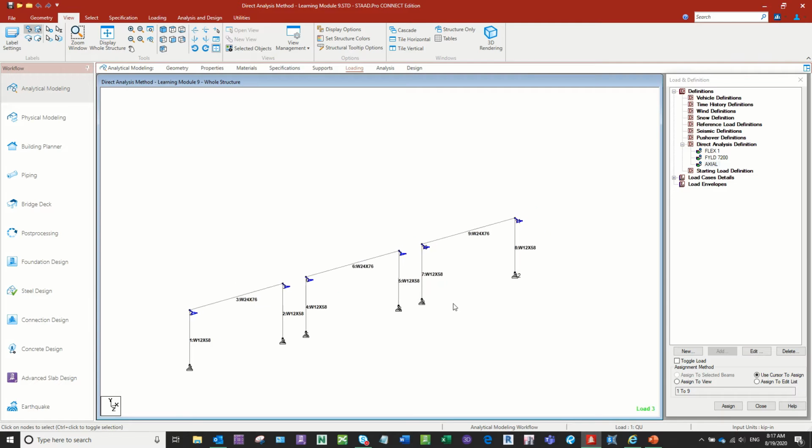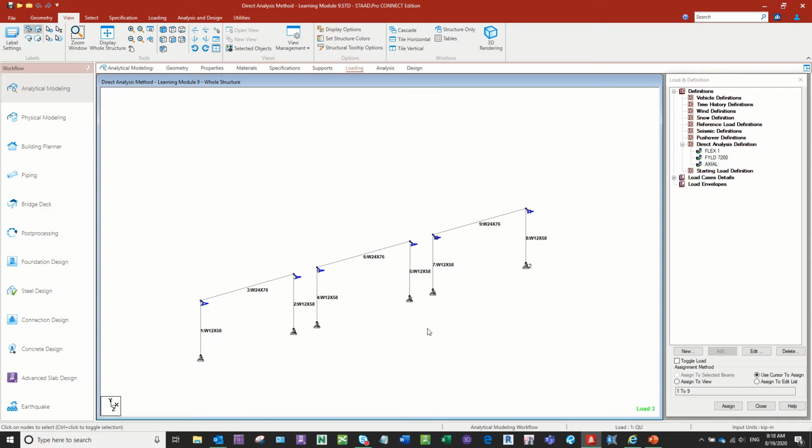And by stability here, I mean, in this case, the ability to maintain its equilibrium, its structural capacity in a deformed shape, and not have extremely large deflections. So that's essentially what we're checking for. We're going to design these columns and these beams for moments and axial forces and shears that are required in order to maintain equilibrium. And that's if this structure is stiff enough just to begin with.